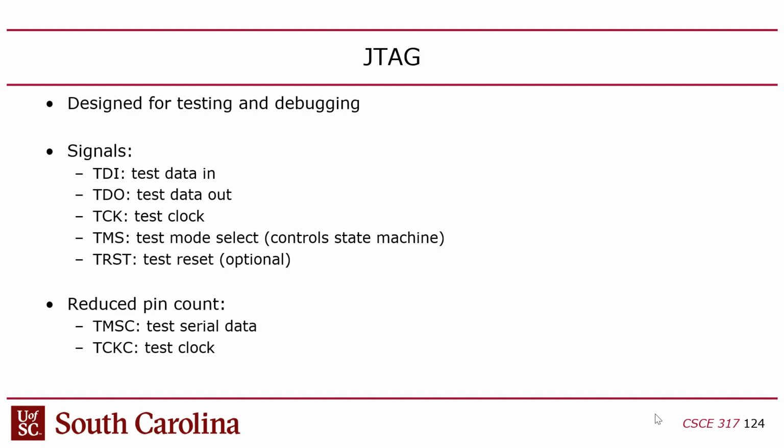But the reason it does that is because the device on the FPGA board that we're talking to is called a USB Blaster. The USB Blaster is actually putting JTAG over top of USB. So the way it really works is you have USB on the bottom level, you have JTAG on top of that, right? And then you have UART on top of the JTAG, right? Kind of complicated. It also explains why things are kind of clunky when you're communicating with the board, right?